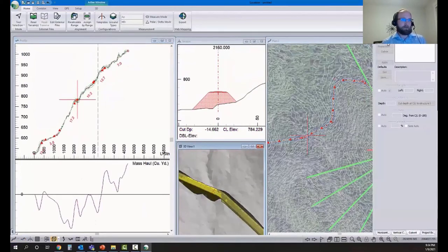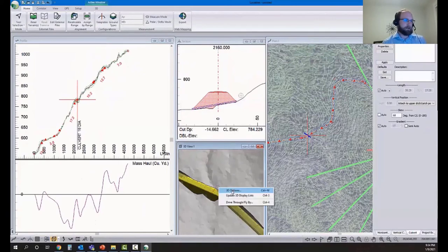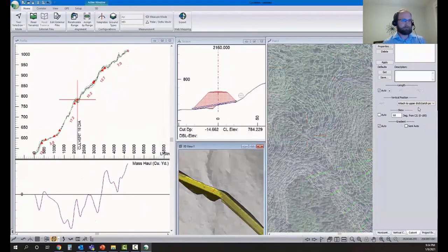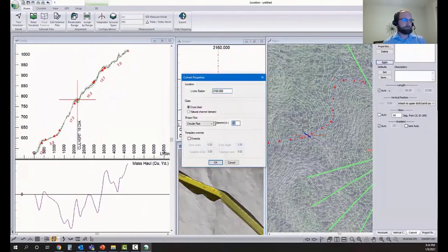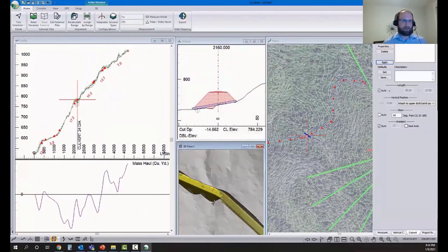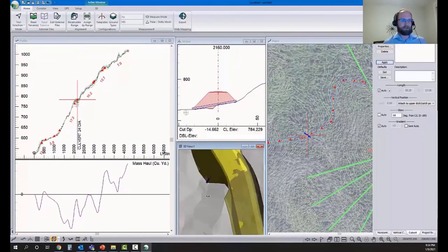And then we'll come over here and we'll add a culvert. So I'm just going to do one culvert in this example. It's all kind of the same. I've added that in our location. I'm going to just change the 3D setting so we can actually see the culvert. And we can change diameter. We can also change structure type. I'll adjust it here momentarily.